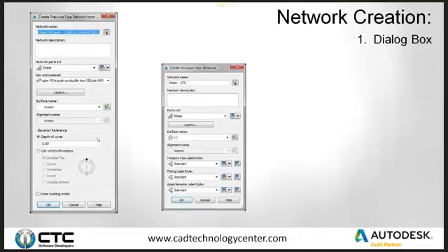So a lot of people build their alignments with a polyline and then turn it into an alignment. Pressure pipes are no different. I can build a polyline of saying, hey, where do I want my line to go? And I'm just going to say, build a network based off of that line. And in this example, you'll see that it's got a parts list of water, kind of like the list that we just generated, or I showed you some screen caps on.